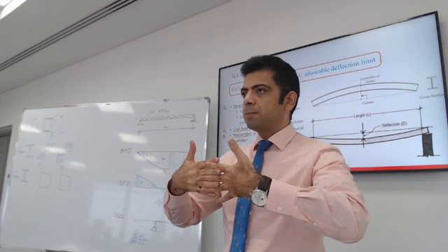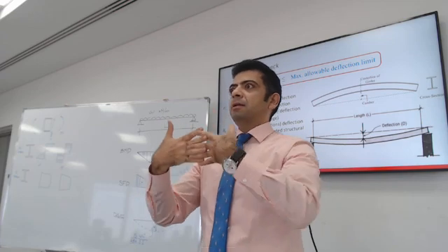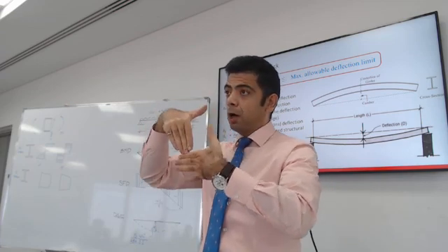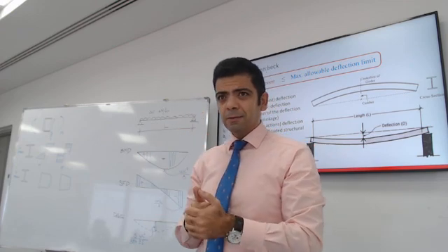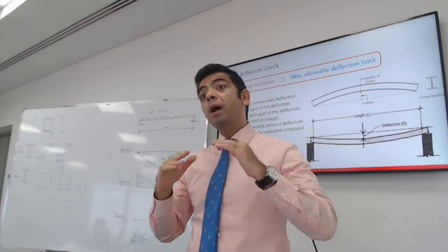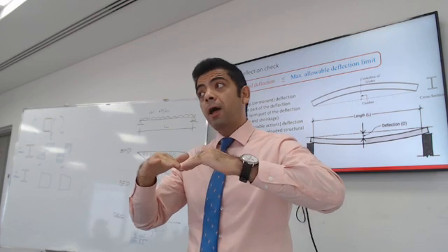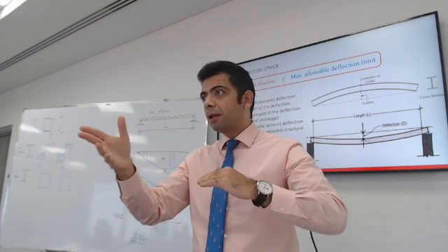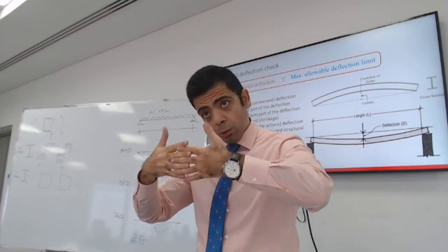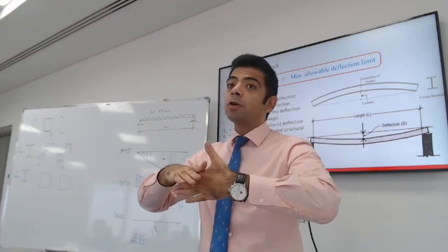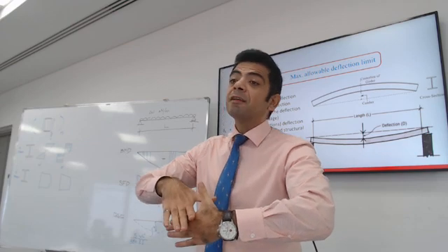Well, the camber is preset. It comes to the site cambered. When you apply load on it, it deflects downward, so they cancel each other. What type of load? What is the first load that will be applied on the beam? The dead load, meaning its own weight, and then anything you put on top of it will keep on deflecting downwards.